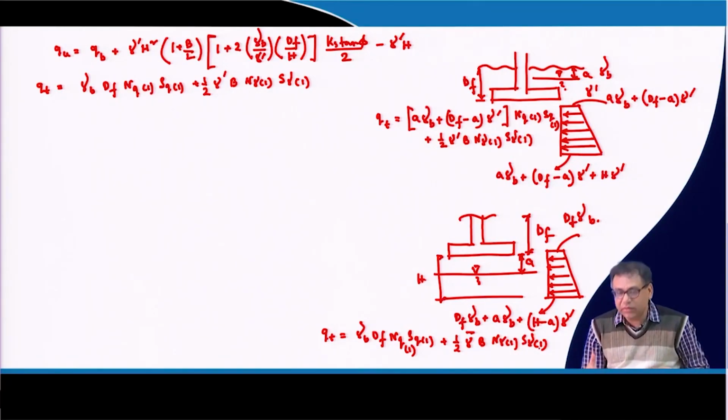Because I am basically doing the same process that I discussed during the effect of water table on bearing capacity in Terzaghi's bearing capacity theory, which I covered in one of my previous lectures. There I discussed how we can incorporate the water table effect in the Terzaghi bearing capacity equation, and that is what I am doing here. Okay.